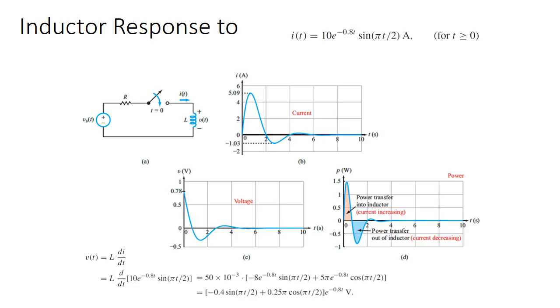So, if this is the equation that we're given, this is also another indication of why it's important to look at inductors and capacitors, RC and RL circuits, at large periods of time. Because over large periods of time, a lot of these circuits are going to balance out towards the end, so the inductor is going to act like a closed circuit or a short circuit, while a capacitor is going to act like an open circuit.